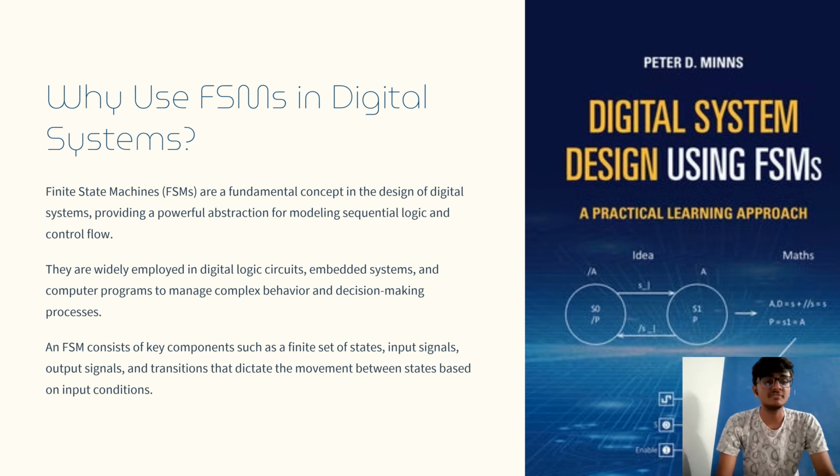The second, more important question is, why use FSM in digital systems? Finite state machines are a fundamental concept in the design of digital systems, providing a powerful abstraction for modeling sequential logic and control flow. They are widely employed in digital logic circuits, embedded systems, and computer programs to manage complex behavior and decision-making processes. An FSM consists of key components such as a finite set of states, input signals, output signals, and transitions that dictate the movement between states based on input conditions.